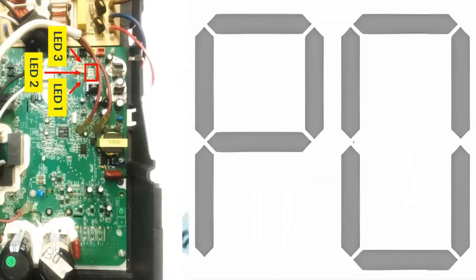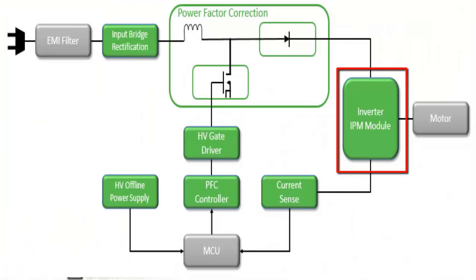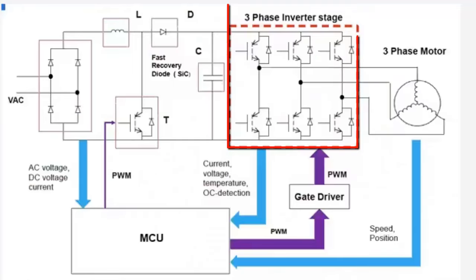10. When the LEDs of the outdoor unit card light up, focus first on the IPM circuit of the external card. The IPM circuit is responsible for distributing the voltage generated by the PFC circuit to the compressor coils. It is recommended to focus on observing the continuity of the traces that transmit electricity from the card.